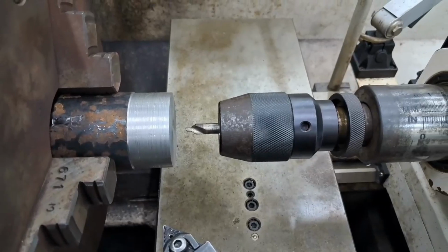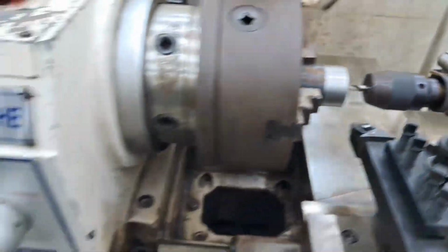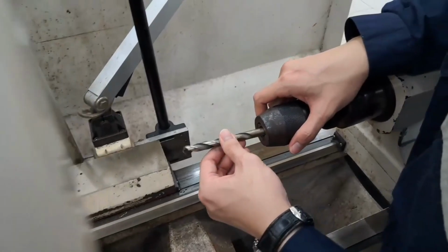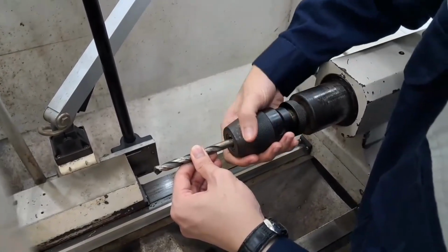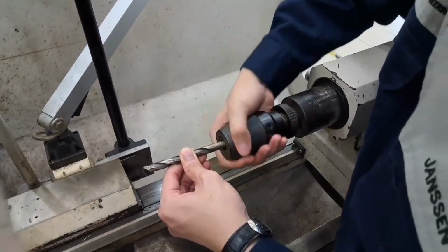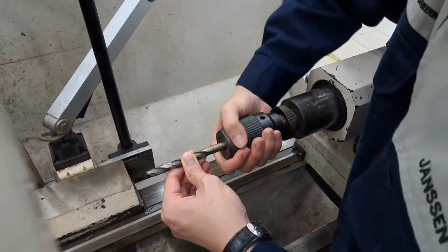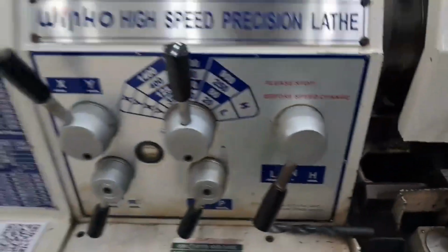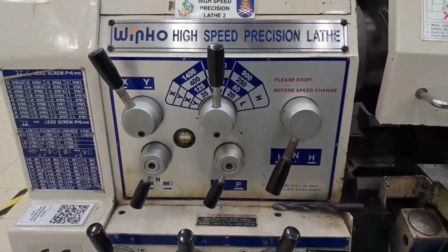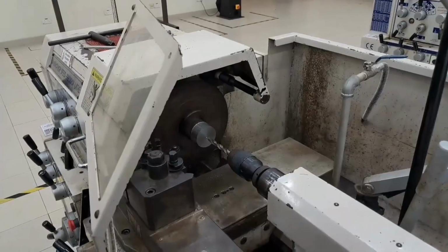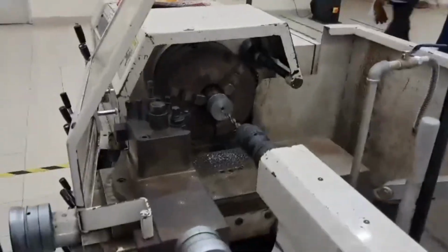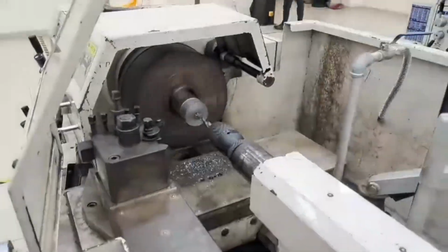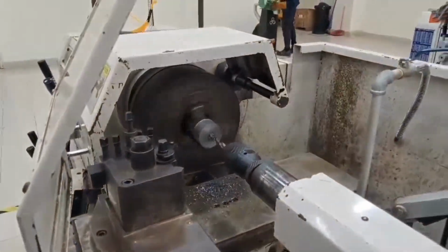The next process after the turning process is drilling on the workpiece. The reason drilling is done after turning is to mark a location and to create a small diameter hole for the boring operation after the drilling operation. The drilling operation is very important. This is to make a hole big enough so that the tool for the boring operation can fit into the workpiece.